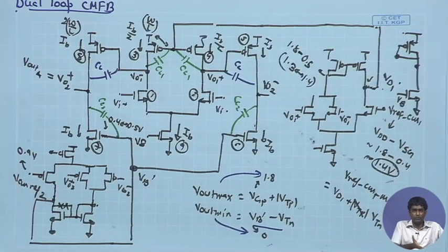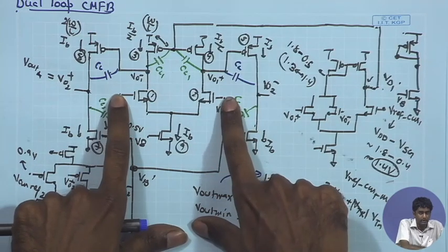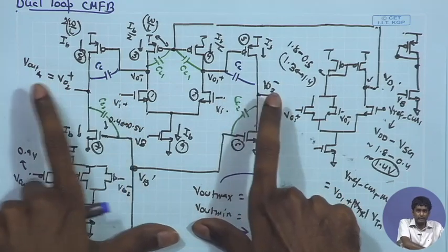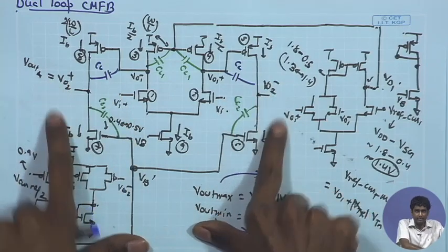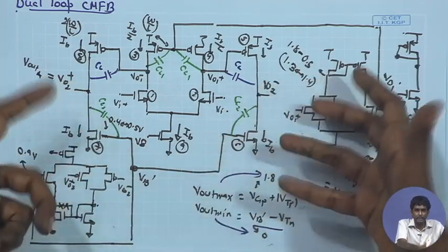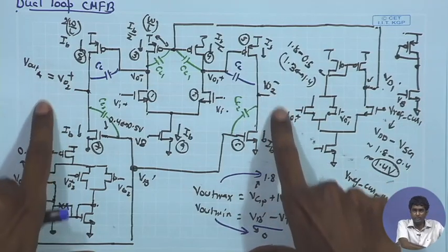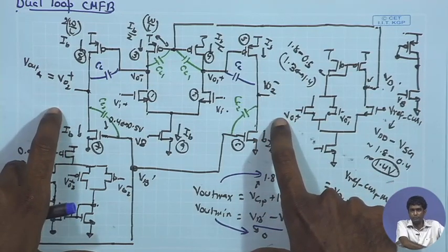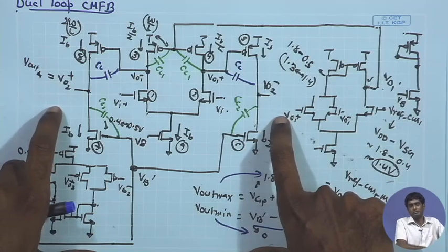And we can also look at the reverse picture, whether the differential mode operation is affected by the CC1, CC2. So, whether the differential feedback, the differential compensation, is having an interference because of the capacitance that you have put for the common mode feedback. So, once again for that I will look at the input signal applied over here, and I will be looking at the output signal VO2 plus and minus. I can use the capacitive feedback and look at the voltage division coming out of that also, as we have discussed. In order to look at the A beta, you need to look at the capacitive division also. So, from here you will be connecting those two capacitors and tapping the center point, and that will give you the A beta factor, that is, the loop gain.